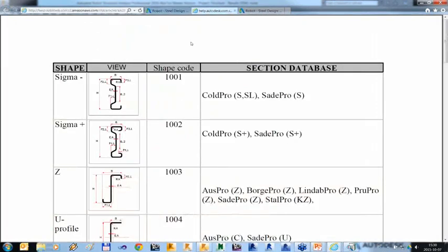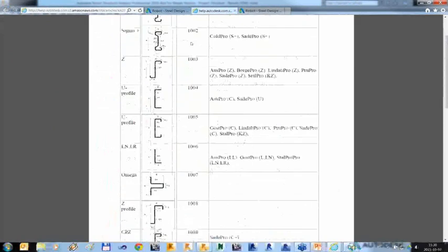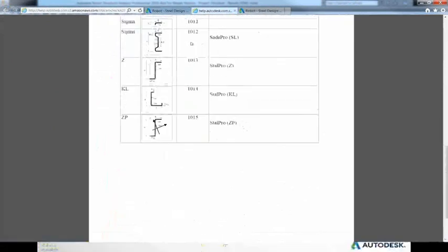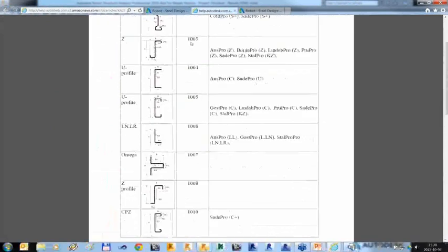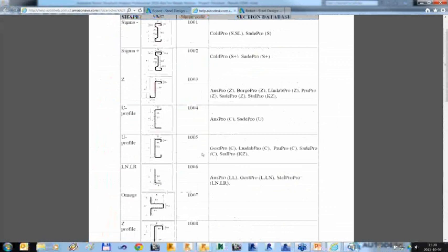I have already opened it, and you can see all available thin-wall section types in this document. So our C section is a kind of U profile of type 1005. It's not only the section type number required to be filled, but also some additional data. After zooming a little, we can see all the required additional data which should be filled in the database.